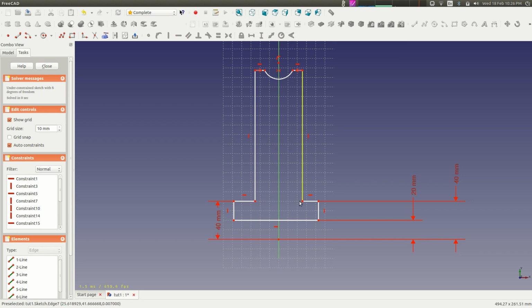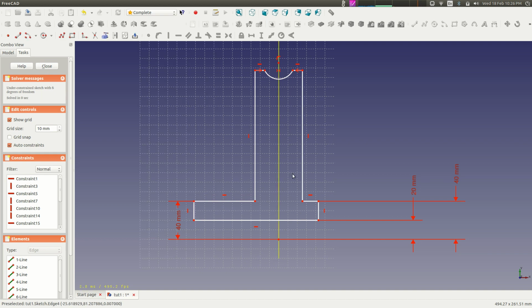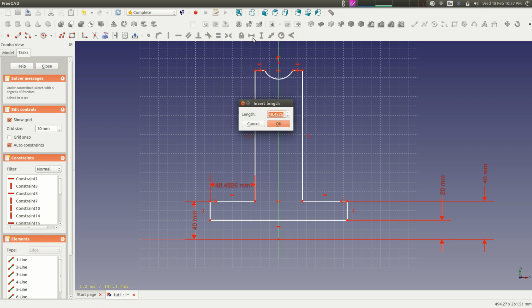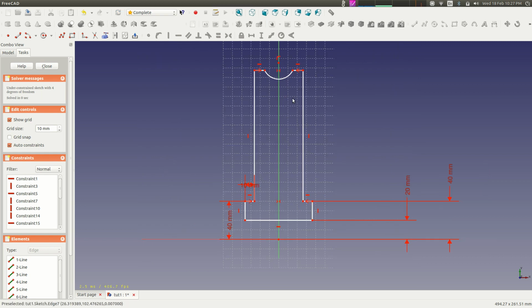So you can see that these two are, maybe I'll move this out a little bit, are greatly different right now. So if I select that point, I want these 2 points there to be symmetrical over this axis. And if I make a symmetry constraint, you'll see that they are now. And so no matter what I change this to be, so if I make this 10 millimeters, the other side will always be the same.